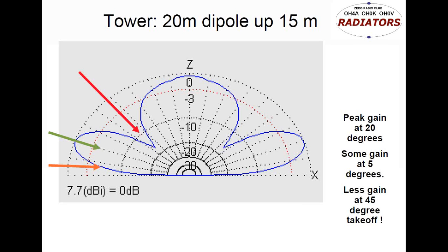There's so much less gain, but on 20 meters there are going to be stations that are coming into your antenna at something like a 35 degree incoming angle and above, and you are not going to be competitive with those. So you need to design your antenna system so that you can also hear everybody coming in with a little bit higher incoming angle or takeoff angle.